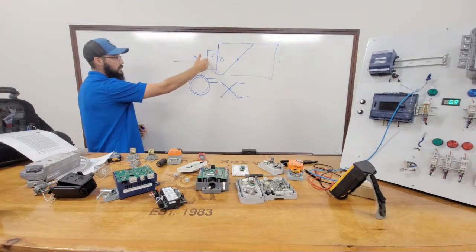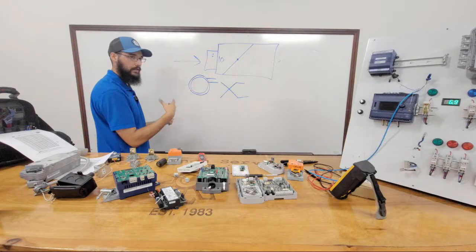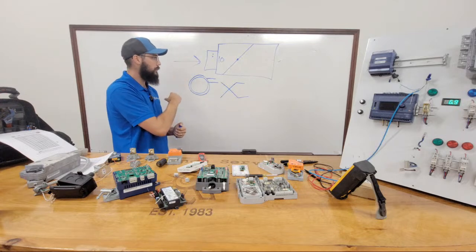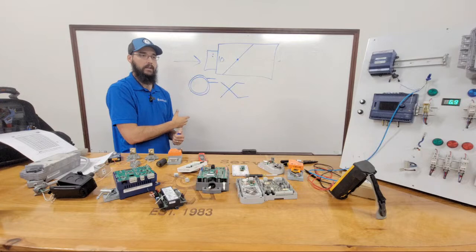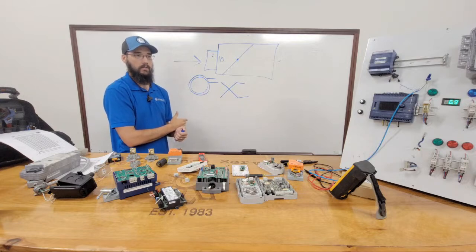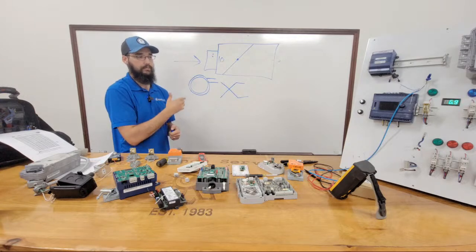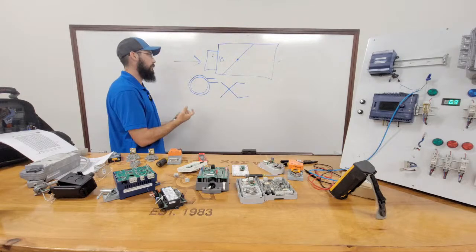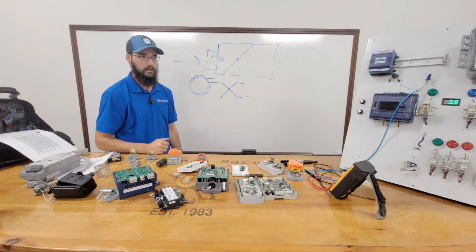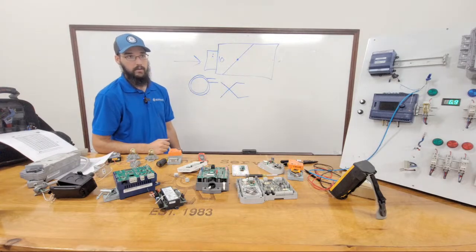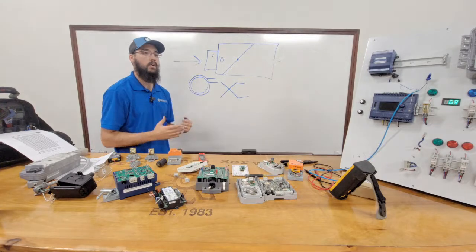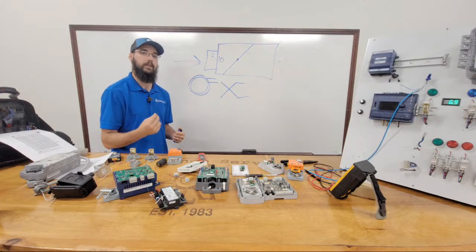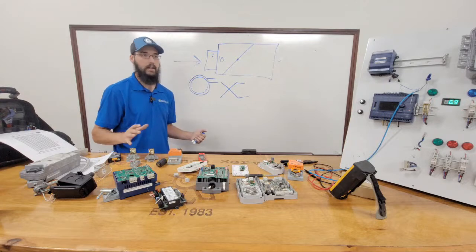Many times, a lot of the time where I see people do this, it happens during the install itself. I see people do this because they don't have enough space to do it the right way. So instead of making adjustments to fix it and relocate things, their solution is we're just going to flex duct to it. It's not going to work, especially if the system is trying to monitor CFM and use that in any kind of way.